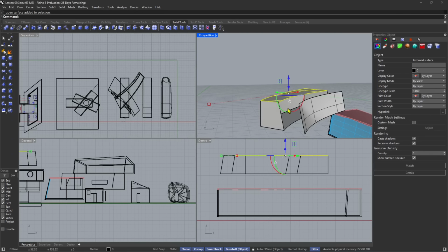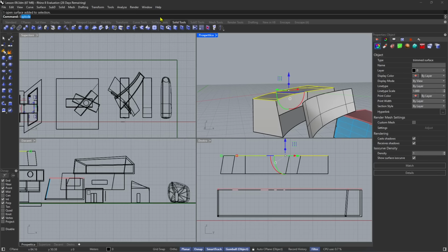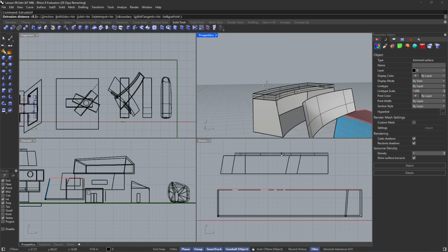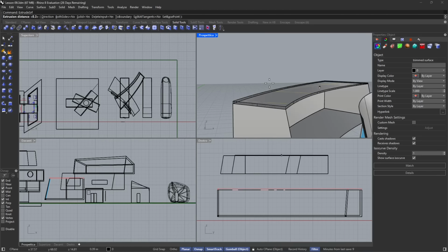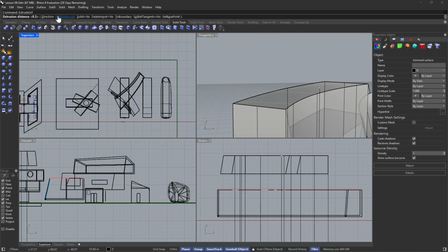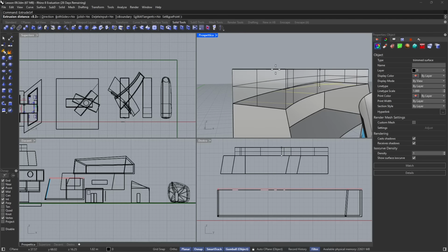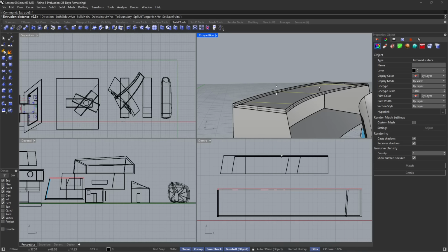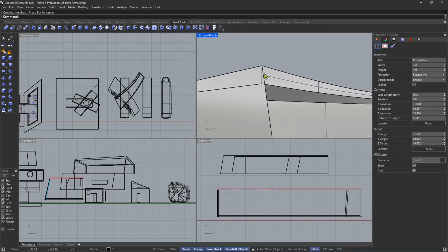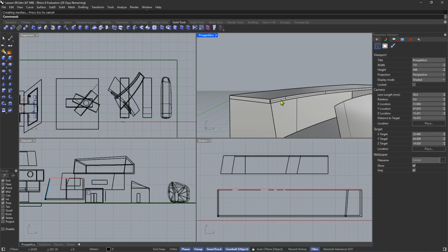Now, if I only use the roof, for example, well, yes, in this case I can extrude the surface and this will work better, because I'm going in only one direction with one surface. You always need to choose if you want to go one side or the other. If you go downside, you will need to fix these corners right here.